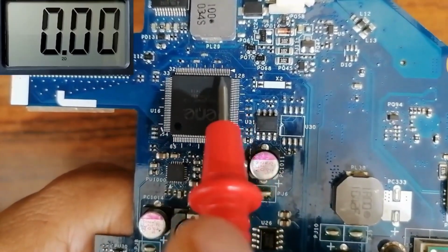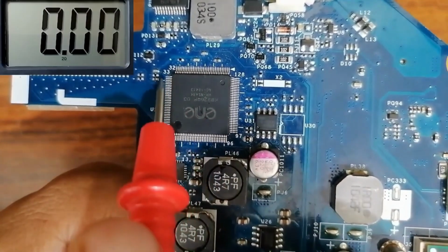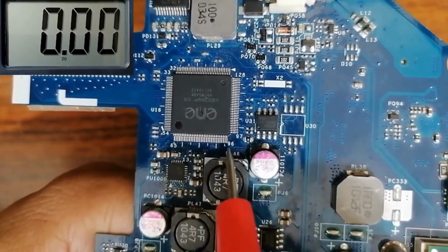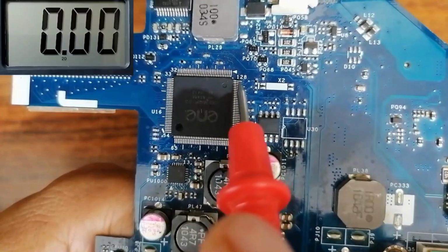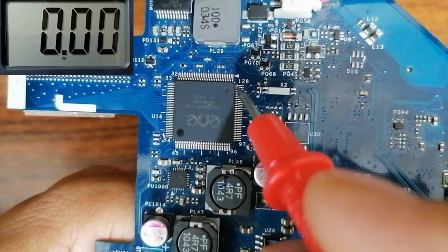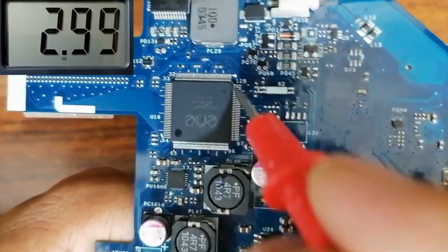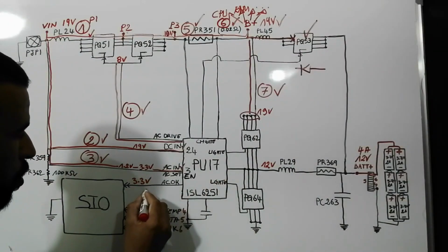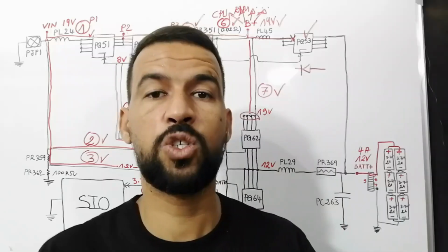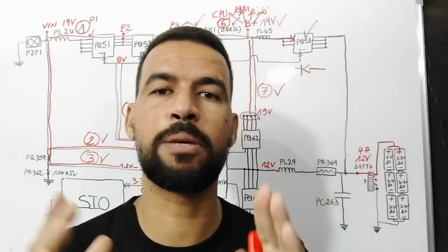The ACOK exists in pin 127, as you can see in the schematic. So let's check pin 127. This mark here means this is pin number 1. Over here we have pin 32, 33, here 64, here 65, here 96, 97, and over here 128. So pin 127 should be this pin. We have 3 volt in the multimeter, so ACOK is good. So step number 8, the ACOK, is good. The ACOK that the charge circuit sent to the SIO is the same as power good.